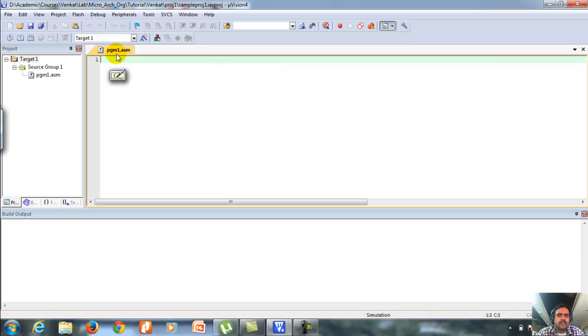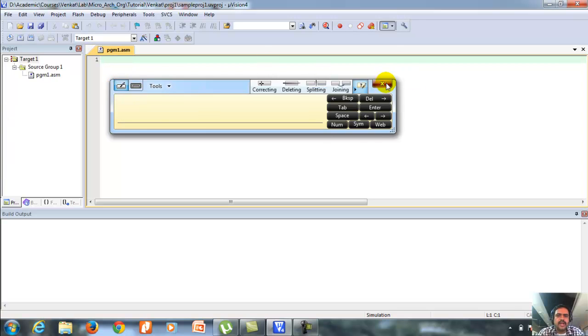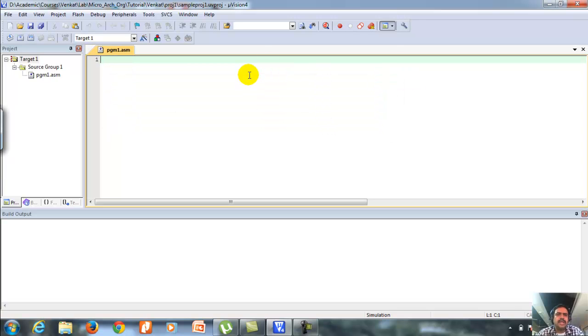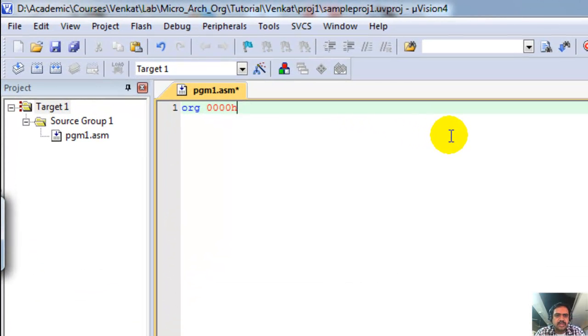First I'm going to teach you how to create a general delay loop. Or first let me tell you how to create a loop in assembly language programming. So this is KEIL. You know how to open a project, how to create an ASM assembly level file, and how to add it to the group. Assuming that you have practiced and know it very well, I'm continuing with the program. As usual, I'm writing ORG 0000H. This is the origin I'm starting from. I say MOV A, #5H.